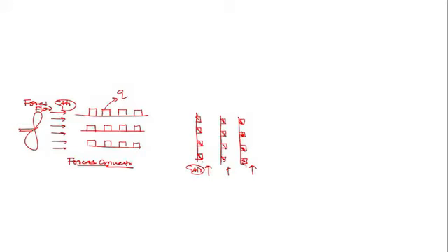The air surrounding the circuit gets heated, and then the density becomes lower, it becomes lighter, and lighter fluid goes up. That causes a buoyancy effect. Lighter will go up and heavier will come down, and in this way the heat transfer takes place. That heat transfer is by free convection. So this flow is basically buoyancy driven flow.